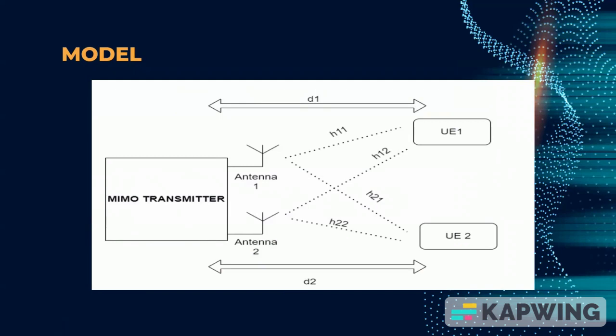When the signal is sent, it will be sent using superposition from the base station to the users. Once at the receiver side, the signal will be decoded using successive interference cancellation. User 1 is the weak user and user 2 is the strong user. So user 2 will have the signal of user 1 also decoded, which will be considered as the interference. Next slide.